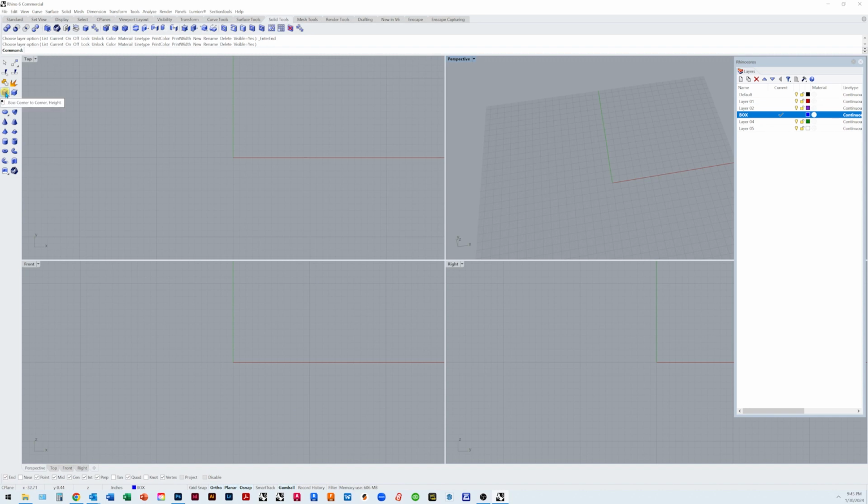That's our most basic. If you click on that, left click, it's going to ask you a couple of things. It's going to say you can build it from a diagonal, a 3-point, or you can just do it from corners. Let's zoom into the origin here. I'm going to turn on my grid snap, and I'm just going to stay on the grid and build a square.